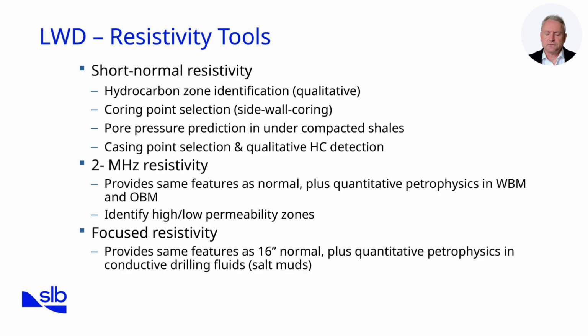It's often used for selecting coring points, particularly with sidewall coring. It also helps predict pore pressure in undercompacted shales, which is critical for safe drilling operations. In addition, it assists with casing point selection and qualitative hydrocarbon detection.